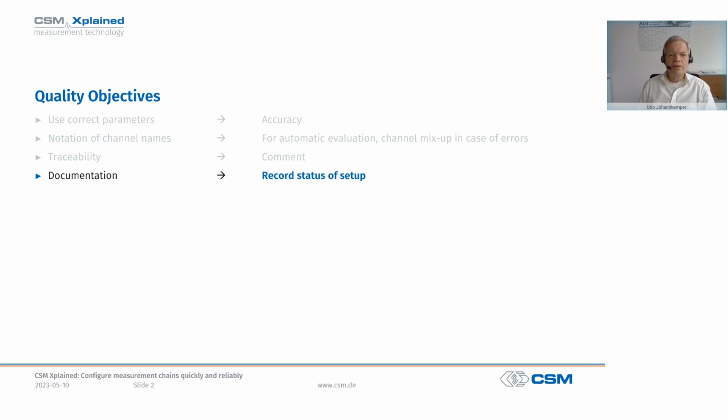It happened to me personally that the final evaluation of a measurement showed unexpected results. The measurement could not be repeated because the test specimen was no longer available. Thanks to documentation, the sensors could be determined and their setting values checked. Thus, the error could be found and corrected. The test was saved. This does not always work, but without documentation, it works almost never.